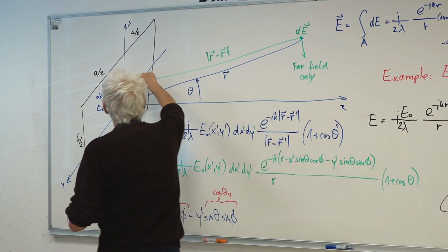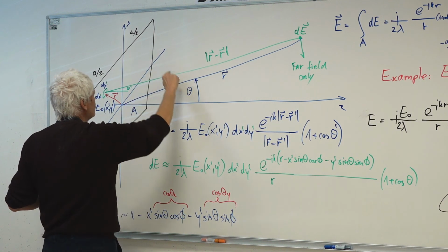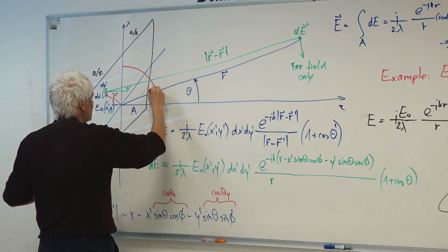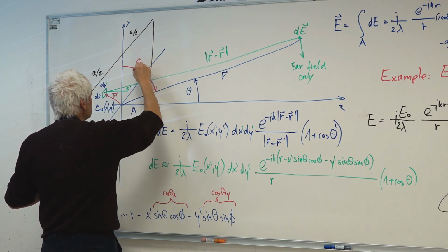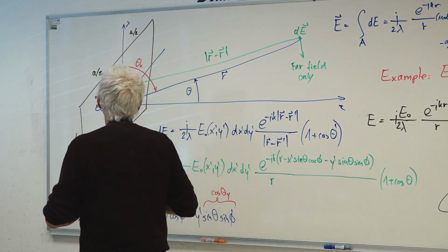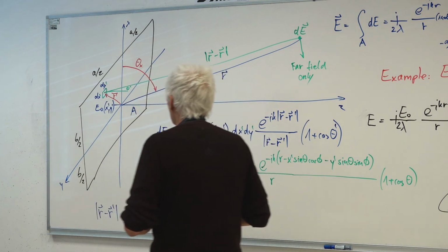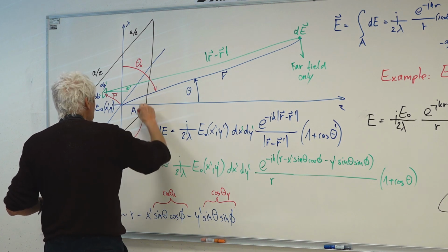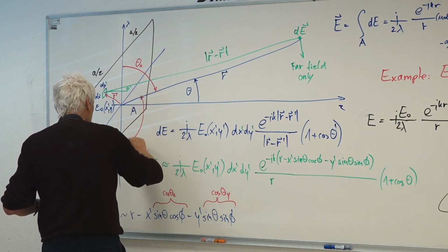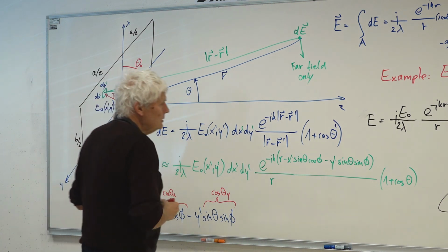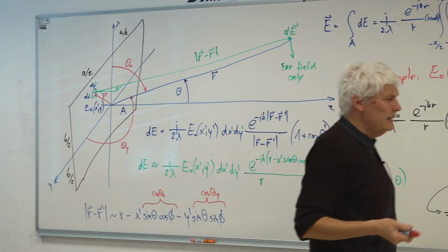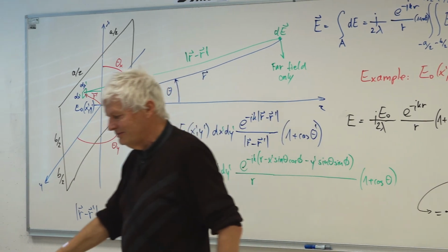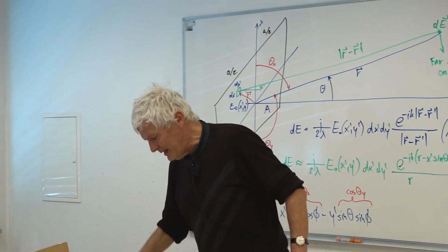Theta x I measured from here to the direction, so theta x is here. This will be the same as rotating my antenna around the y-axis. And theta y is here. So in one plane and in another plane, for instance, I measure the E plane and the H plane of this horn. The two planes I measured, okay?